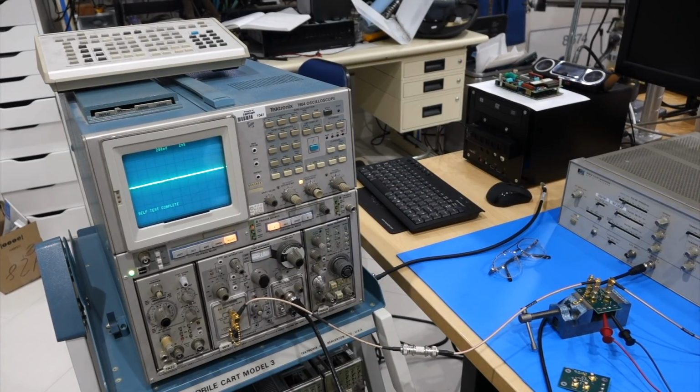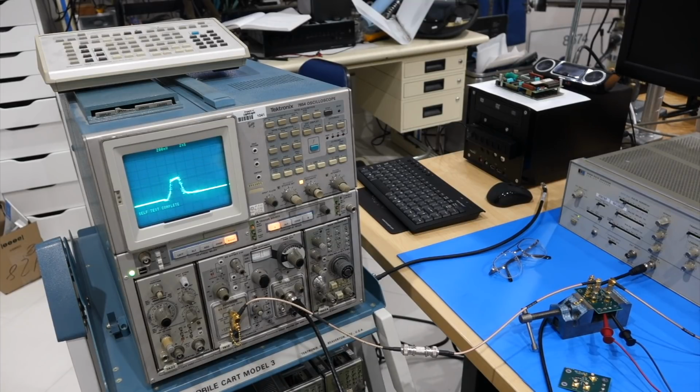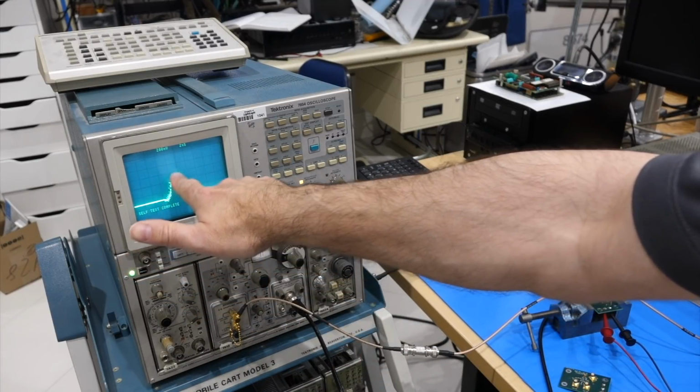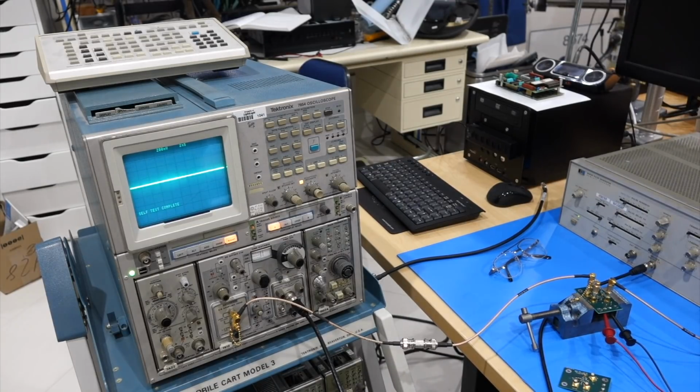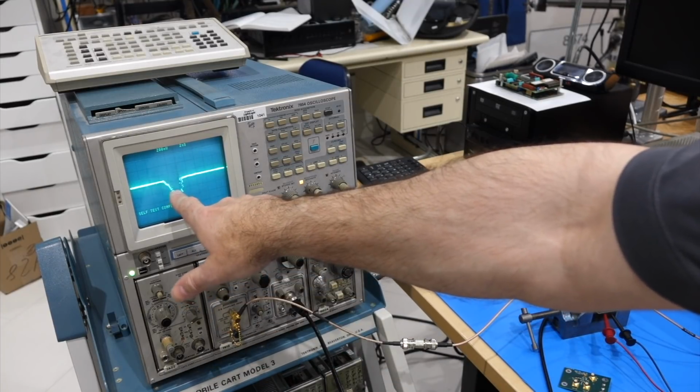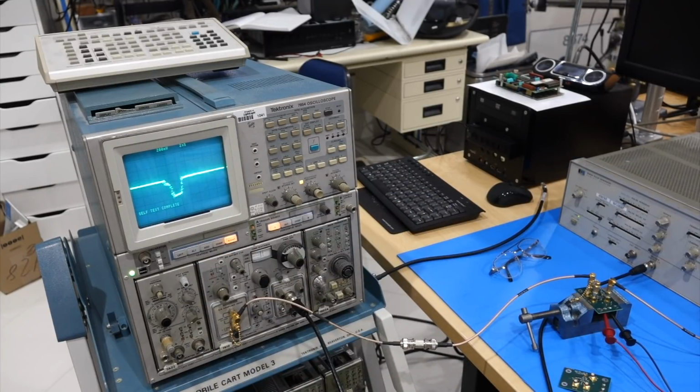Okay, one more time with feeling. I adjusted the bias point down by changing the resistor from 1K to 600 ohms, and well, should be all good to go. There we go, that fixed it. So maybe I might have gotten a little too low, but that's a nice 2-second pulse the other way around, and then let's try the other polarity. And that should be the non-inverted one. Yay! Okay, so I went a little too far, and now the rising edge is a little bit lazy, so I have to just order the right resistor.